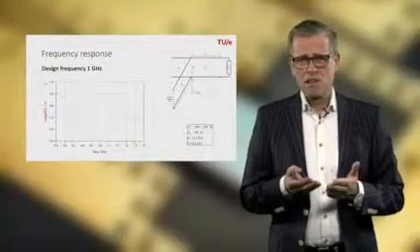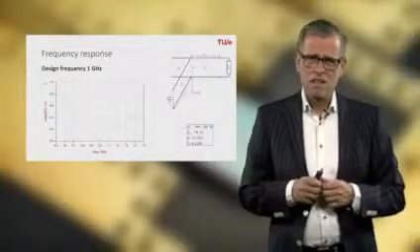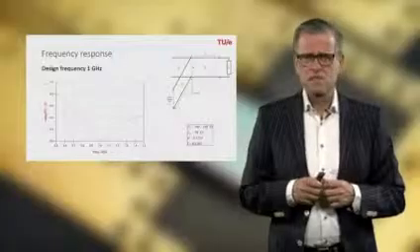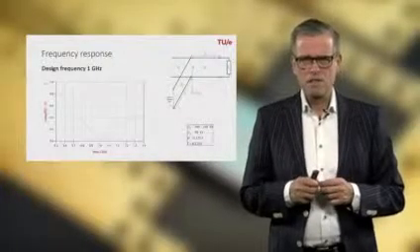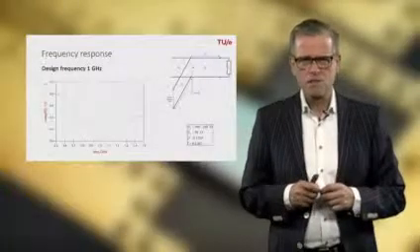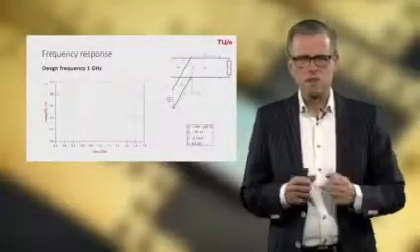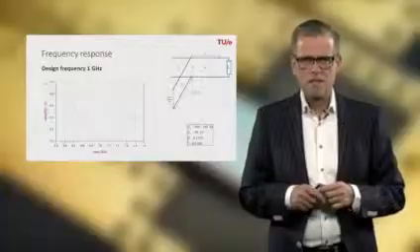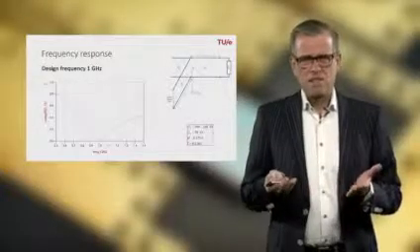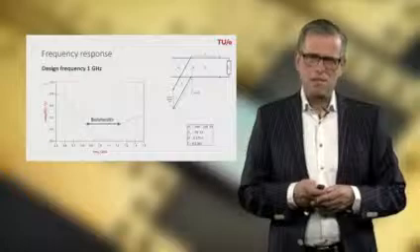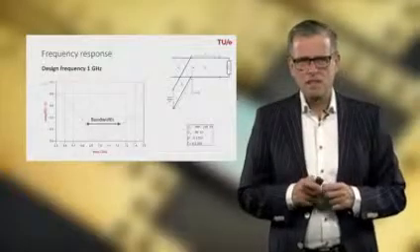But because the line sections, of course, have an input impedance which is frequency dependent, only at the design frequency we have perfect matching. If you go off the design frequency, you see that the input reflection coefficient of this circuit is increasing, which means in practice that this circuit will have a limited bandwidth. And the bandwidth could be defined as indicated here.